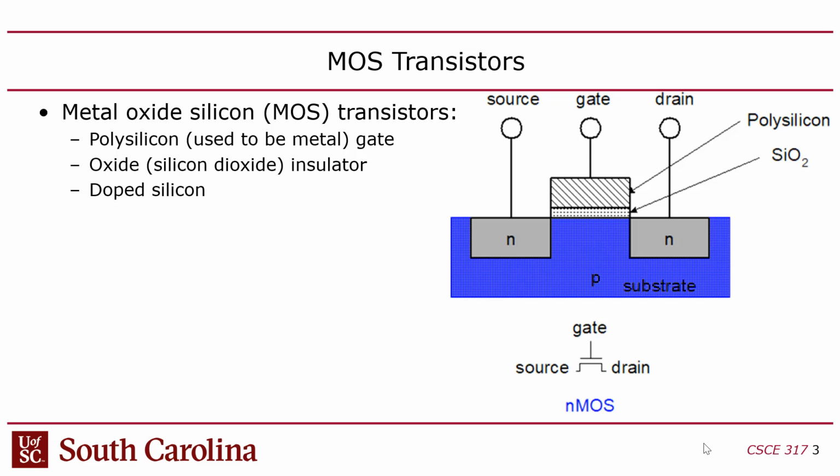As long as the P substrate is grounded, you want to make sure that you keep the substrate grounded, because as long as the substrate stays at a lower voltage than the diffusion area, the Ns, then no current will flow. You'll get that effect where the charge carriers move away from the junction between the diffusion area and the substrate, right?